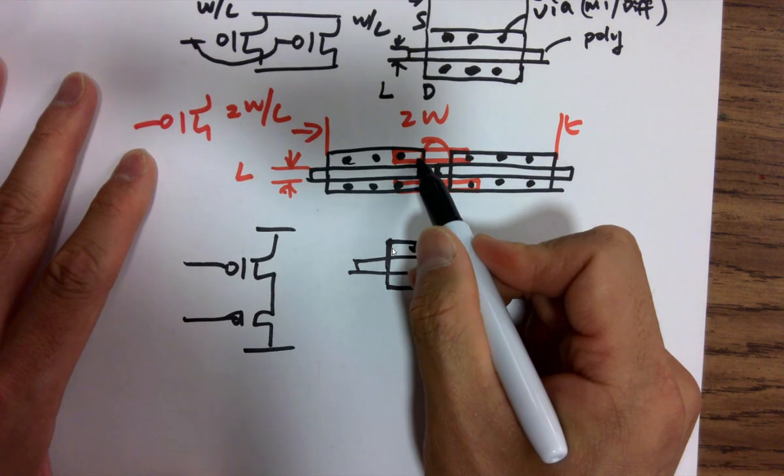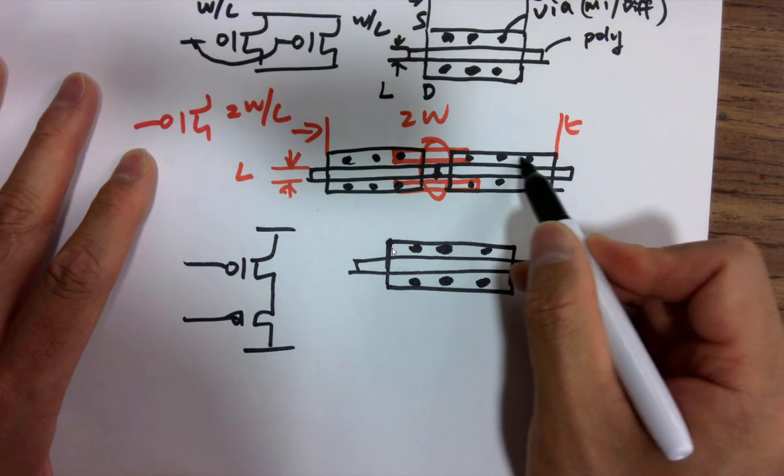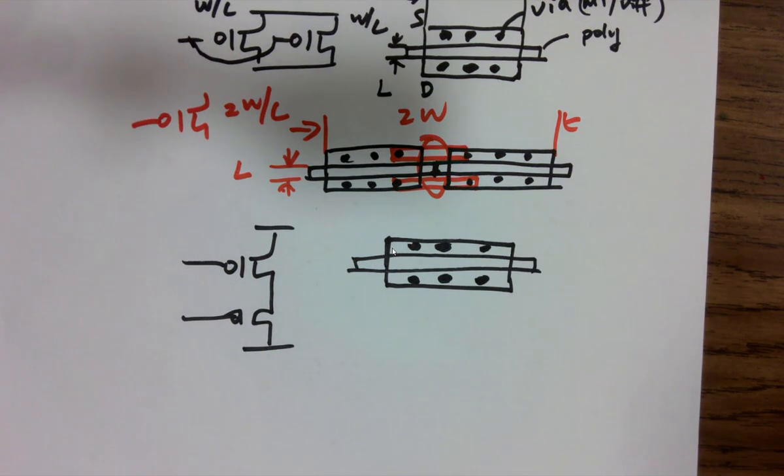why are there multiple vias? Oh, yeah, the area is bigger, so we directly add backup vias to it, right? To improve what? The time delay? No. Sometimes, yes, a little bit. You're right, partially. But also what? Reliability? Yes, it increases the yield. So you have backup vias. If one of the vias is failing, you still have multiple other vias making the connection. So it's improving yield. And yield is a big deal.